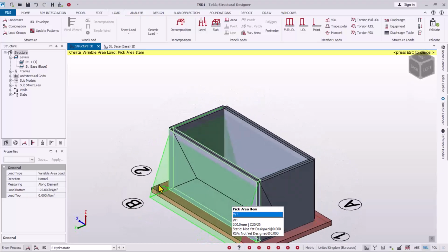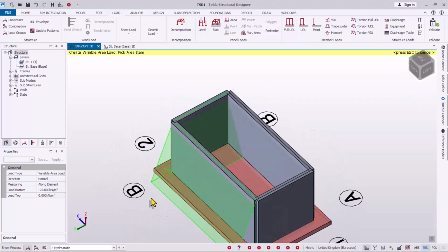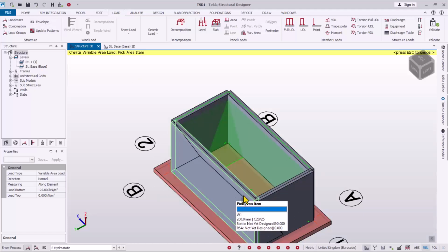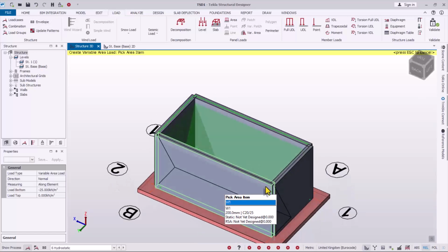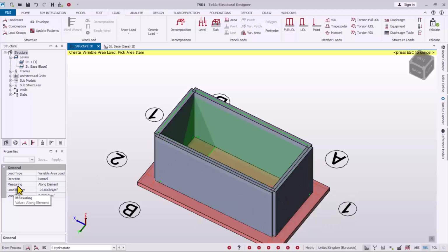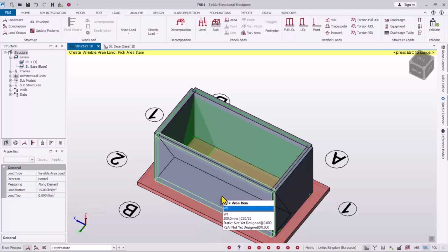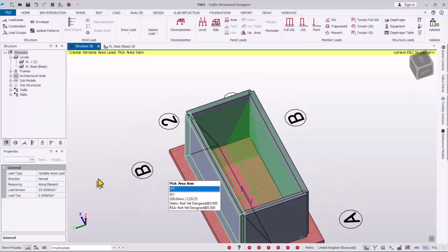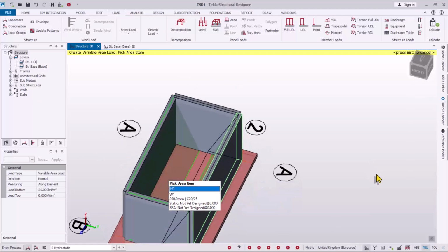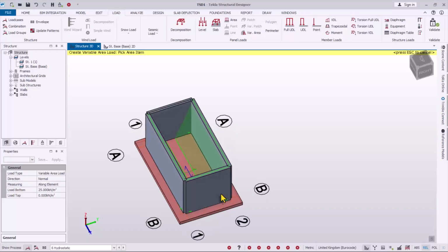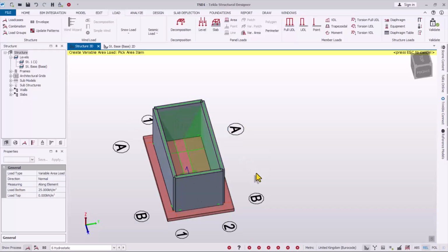Okay, this is applying outside. All right, so which is not correct. You have to undo it from here and then apply from this side. That is applied successfully inside. Okay, so in this direction we need to remove the minus sign we had right before 25 kilonewton successfully, and then we'll be able to apply it here. So if you check, you notice the hydrostatic load is applied inside of the swimming pool successfully. So click on this other wall to have it applied successfully.